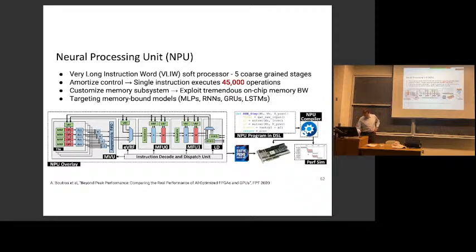It's highly parallel. Inside of it, it's got a couple of different register files and a whole bunch of dot product engines, because matrix vector multiplication can be thought of as a whole bunch of dot products being done together. And that's the biggest module.